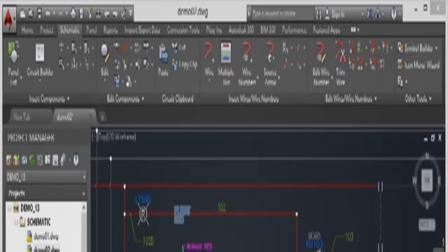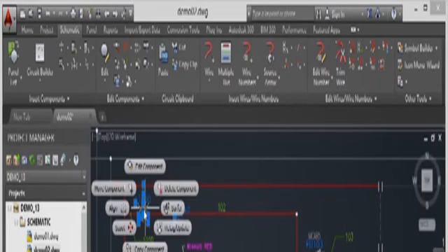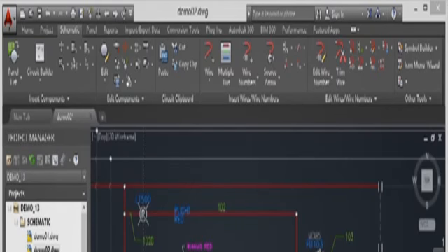You select this component, right click, and when you select Align here, it assumes that the selected component is the master component, rather than when you go to Align up here and you select Align like that, and you've then got to pick the master component you're going to align with. So just be careful of that one. It is a subtle difference, but it's very, very easy to make a mistake. Hit escape there now just to cancel that command, and that's how you align your objects in AutoCAD Electrical.